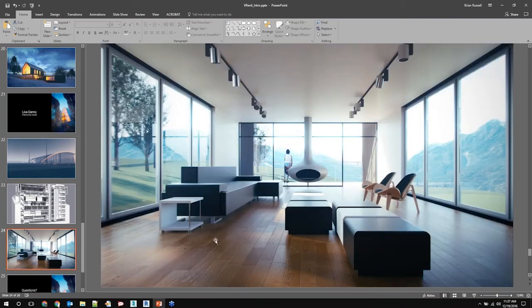And here we're doing something, and I'll show you this in just a moment here, where we're using bloom and glare effects in the V-Ray frame buffer to get a softness to the overall light. So we're not doing much actually with interior lights here. We're getting a lot of the light from the exterior. We're again using HDR imagery as our background lighting source, pulling that light in and then using bloom and glare to add a softness to the overall scene.